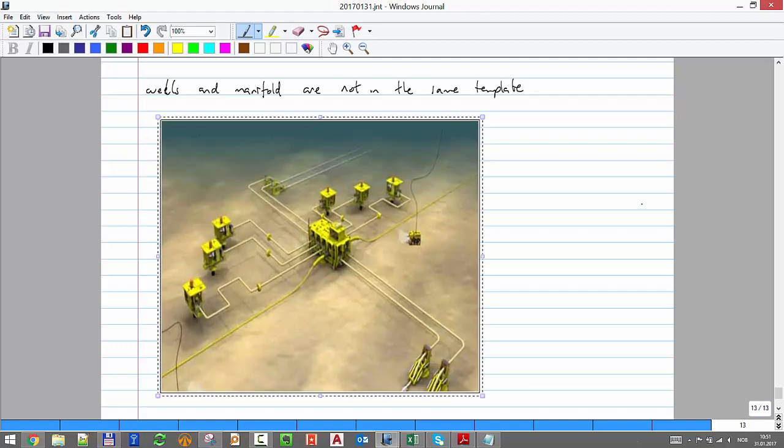So you have every well, all of them, these 6, they go to a manifold, and here is where you have this arrangement. You have 2 valves for each well, and you have 2 lines that go through it. And if you execute pigging, probably you're going to go through one line and come back from the other line. But it's exactly the same. The thing is that the manifold is outside.